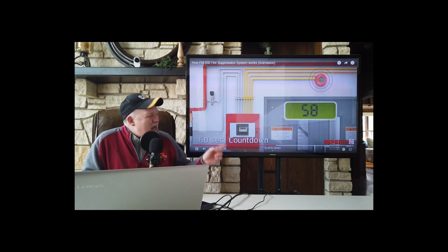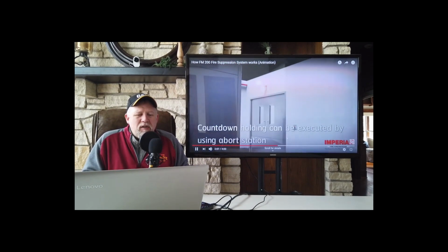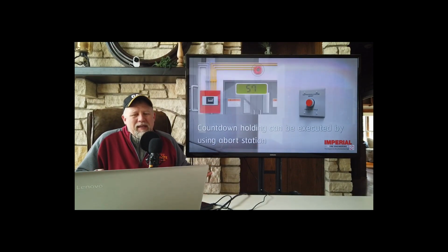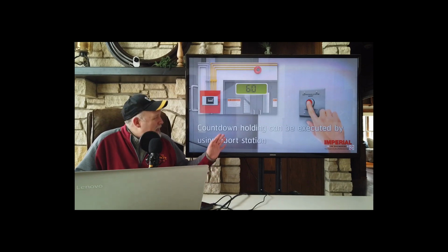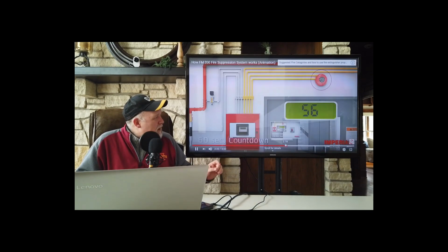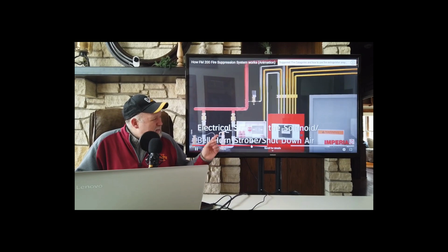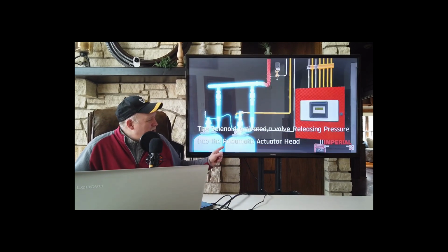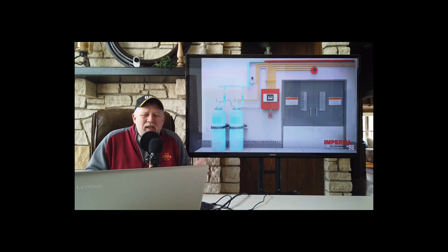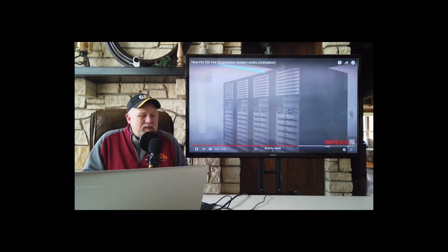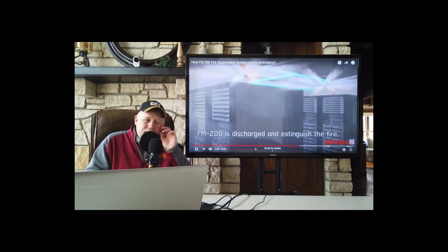Now it starts a countdown to the discharge. Now, the countdown can be aborted. If there's somebody in there and they're like, wait a minute, that's a malfunction, or there's some reason I can't get out, or I don't want that to go off, you can abort the system. Now, just keep in mind, for a room of about this size, you may spend $100,000 on the extinguishing agent and the system. So you really don't want that system to discharge unless there really is a fire. That's why there's an abort button.